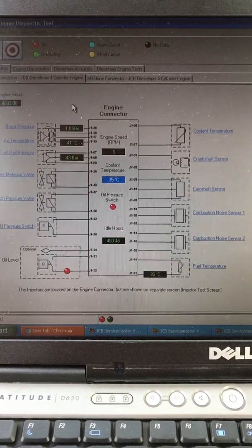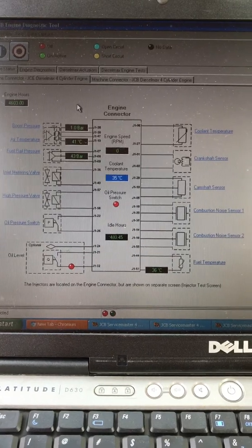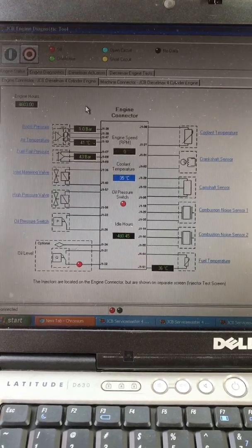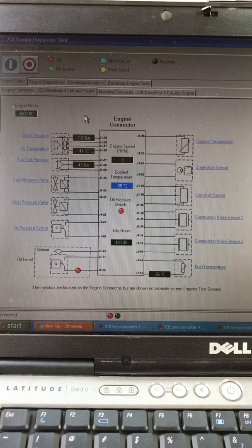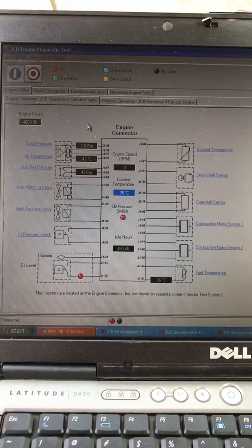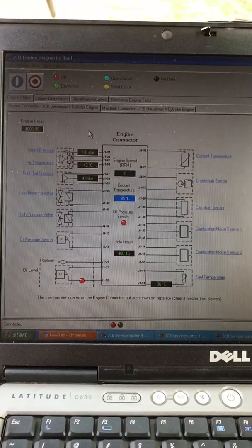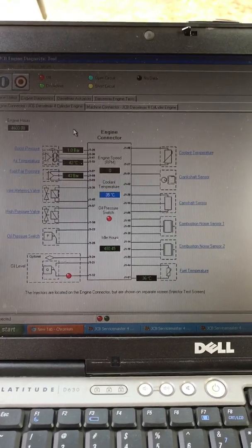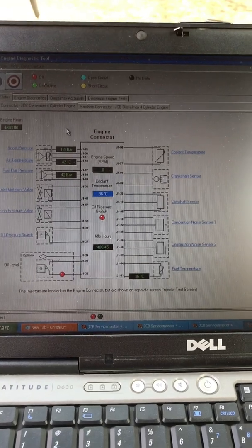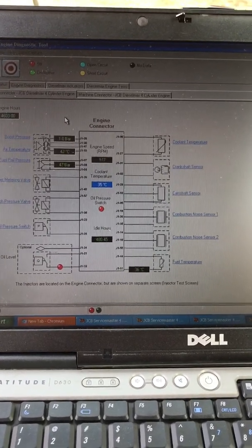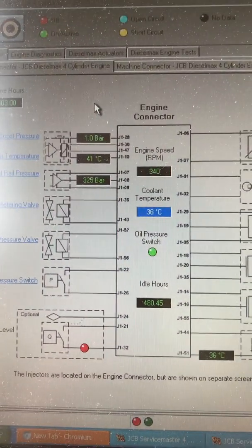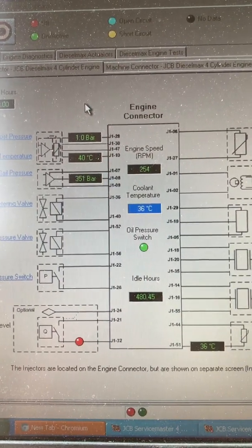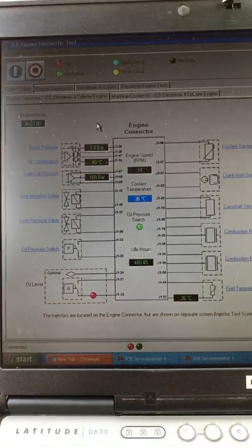So I tried to start 3 or 4 times already, but the engine can start one time and then shut down automatically. On the other hand, I suspect the fuel injector, because the fuel pump gear has broken and the metal debris has already gone into the fuel system. So that debris is the kind of material that gets into the injector and causes no injection. So I tried to start again. Here, as you can see, 5283. This fuel rail pressure is really good enough to start the engine, but the engine still cannot start. Okay, yeah, so I have to recheck the fuel injector.